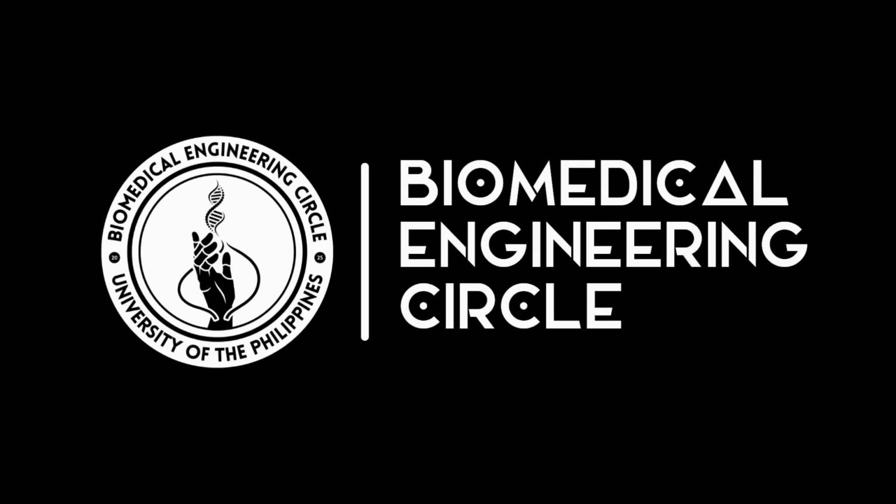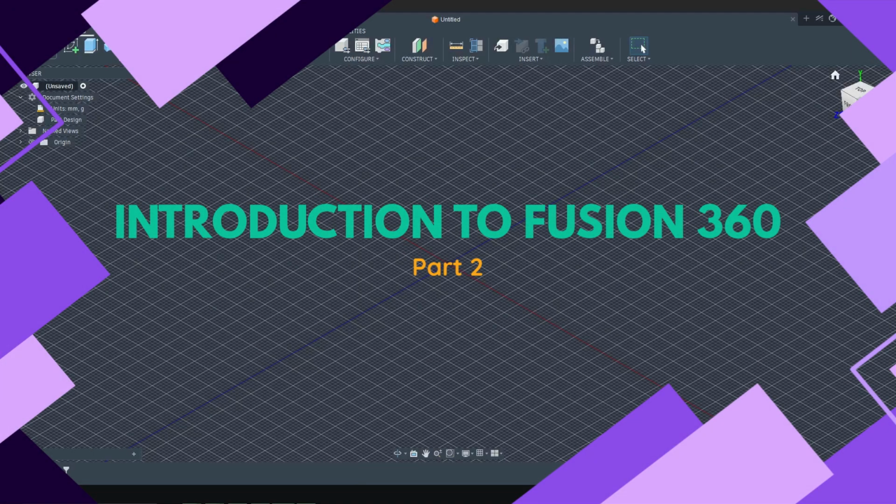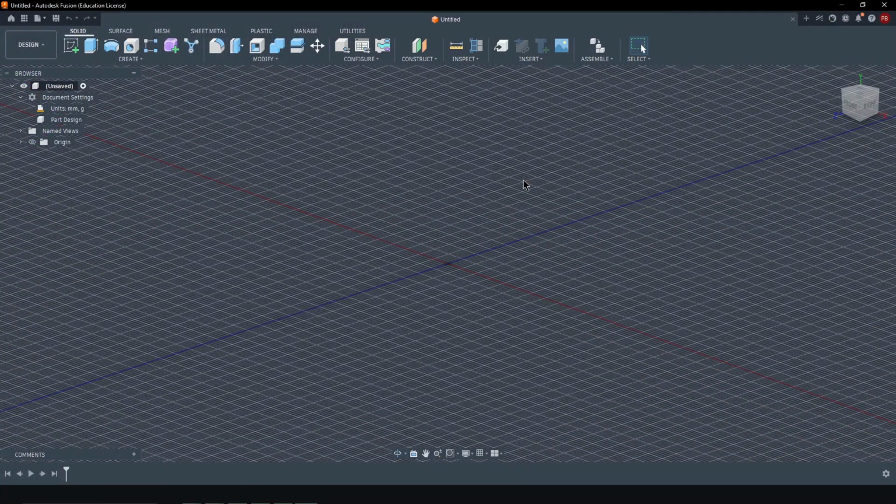Hello! Let us start with creating the main barrel of our 3D model. So in Fusion 360, in order to create a 3D model in the solid workspace, we first sketch, then we extrude or revolve, followed by modifying that 3D model in order to reach our desired shape. So, to create the main barrel, of course, we have to sketch a circle.